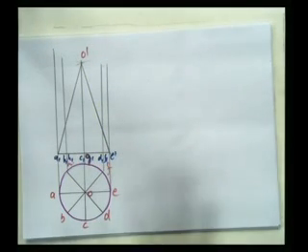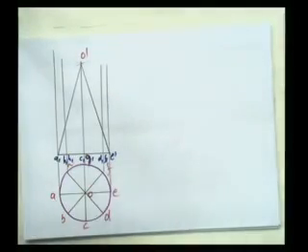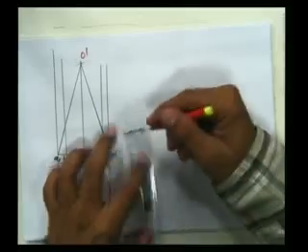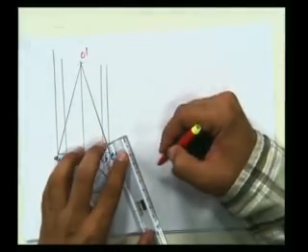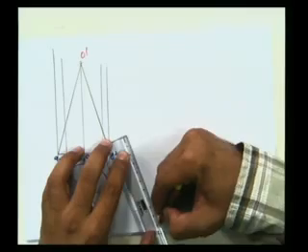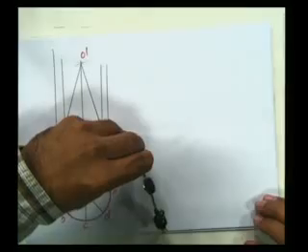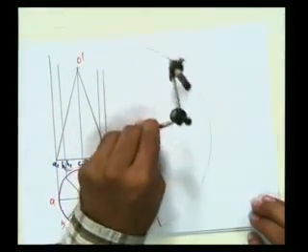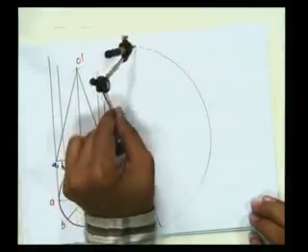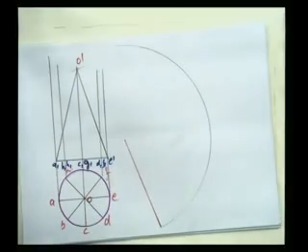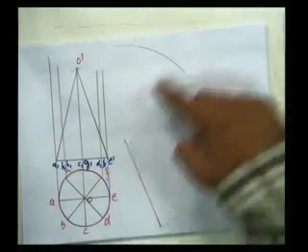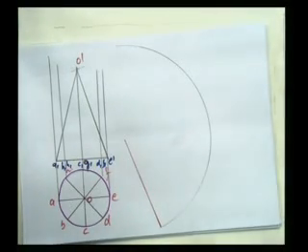Right, first I'll draw the developed surface of this. For that I need to do the calculations. I have this length, so I'll just start from here so that the whole thing is completed. I'll draw a line parallel to it, 10 centimeters, and this is the 10 centimeters that I have taken. I'll draw an arc. Now I need to find out which segment is going to be the end segment. For that I need to do the calculations.